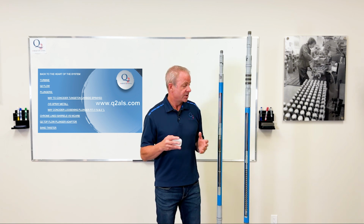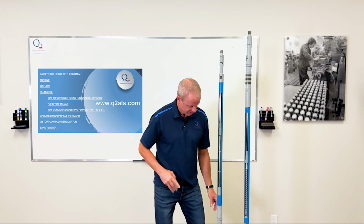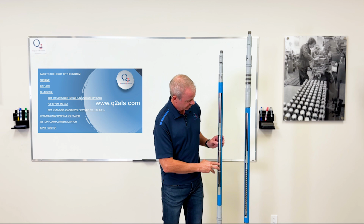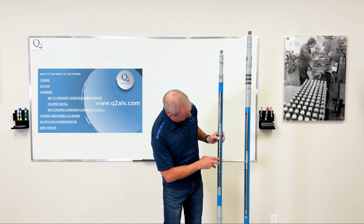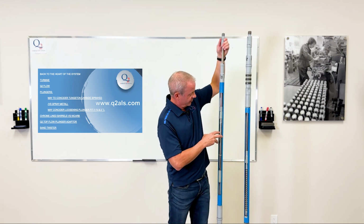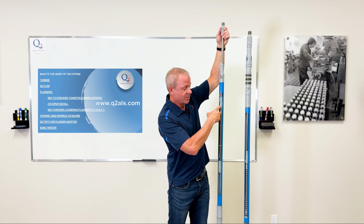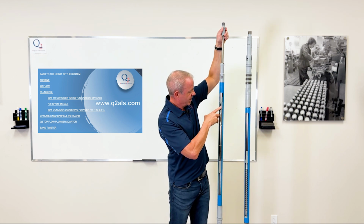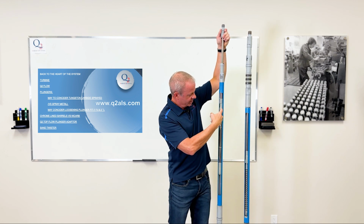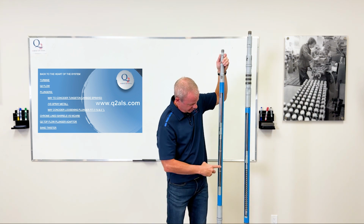The plungers, now there are different types of plungers. In this case, I'll just point you towards this. This here, for example, is a bottom hold down, right? And you've got a spray weld plunger on here, and then you have a Monel pin up here as well. This is sometimes where some of your sand comes down and falls down the side of your plunger. This is not a sand twister. A sand twister is very similar, but it has wormholes that come up, with a beveled edge, so sand can't get caught in there and does not come down and score your plunger. But even if sand does come down here, these little grooves help a little bit, right?